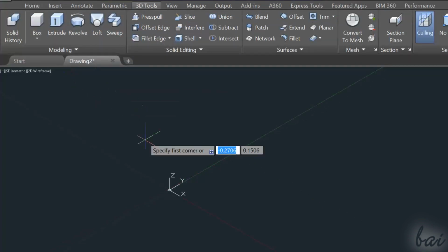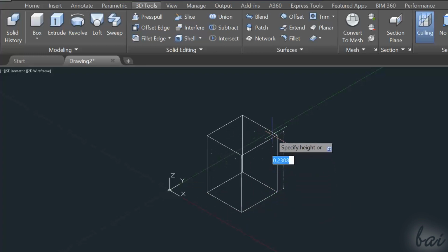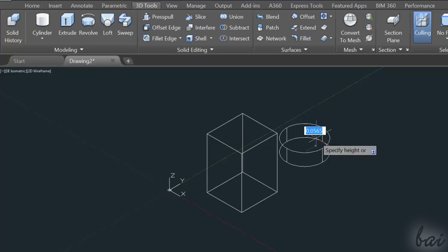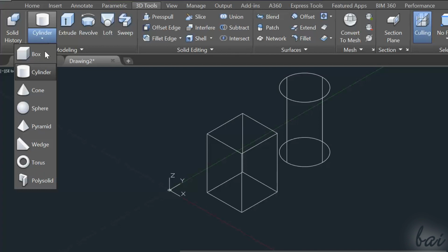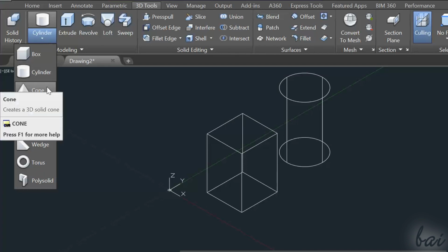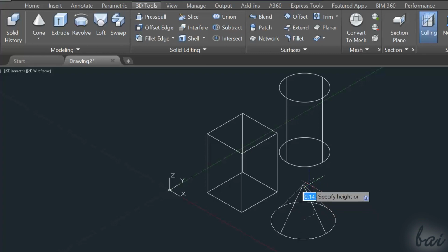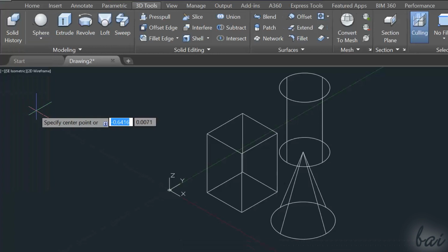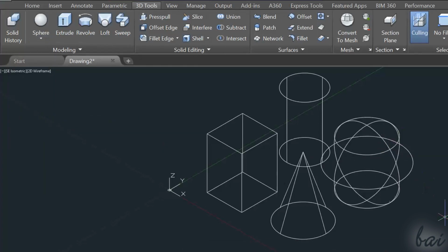The first button is used to draw regular 3D objects like cubes, pyramids, and spheres from scratch. Click on the white arrow and choose the shape you want to draw. You always have to define the base and then the specific height or extrusion. Apart from the sphere, that needs just 2 general points fixed.